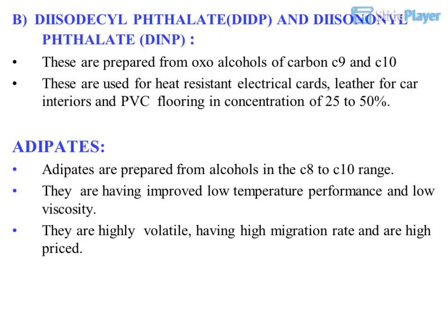Adipates. Adipates are prepared from alcohols in the C8 to C10 range. They have improved low-temperature performance and low viscosity. They are highly volatile, having high migration rate and are high-priced.